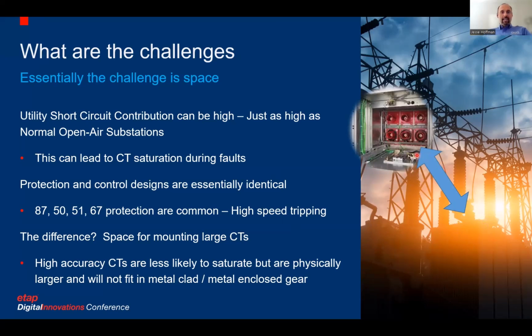Our problem is that within the medium voltage equipment, the metal clad switchgear here, there's limited space. It's a very compact design. What you're looking at inside of this breaker cubicle right here is the stabs for each of the three phases of the medium voltage breaker. And then this square red portion right here is the actual CTs that mount on the breaker stab.